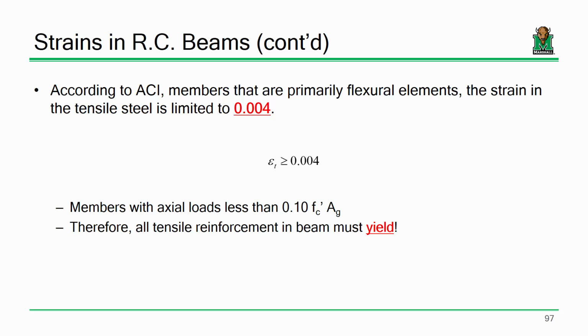I have two components in a reinforced concrete beam: the steel and the concrete. If I bend a reinforced concrete beam, I have concrete in compression and steel in tension. I obviously don't want failure to occur. I'm a structural engineer; I want everything to be fine. But if I'm trying to determine maximum capacity, I have to look at it realistically.